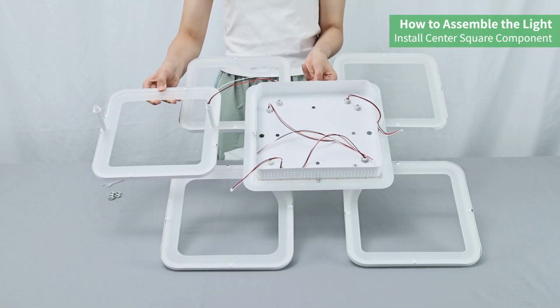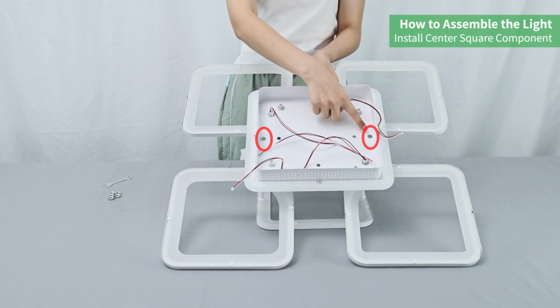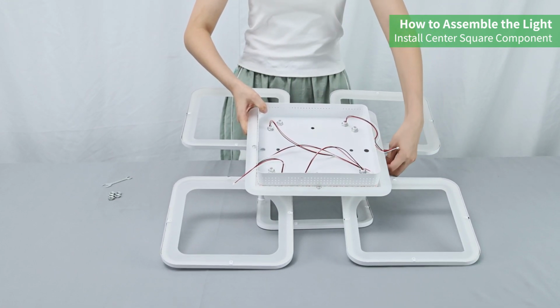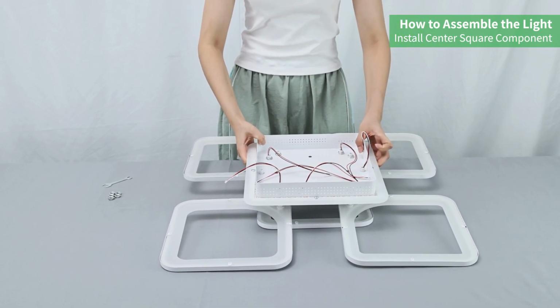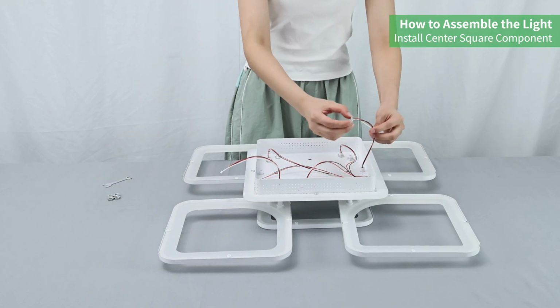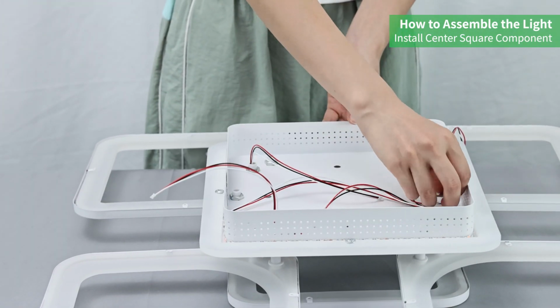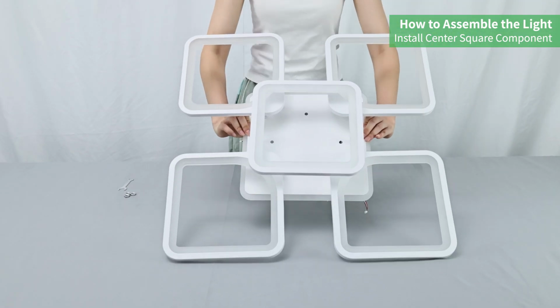Install center square component. Align the center square component with the long tube installed with the pair of holes in the middle of the chassis. Make sure to thread the wire through the hole first, then adjust the position of the fixing tube on the center square component. Use nuts to secure the component to the chassis. Use a small wrench to tighten the nuts. This is what the center square component looks like when installed.